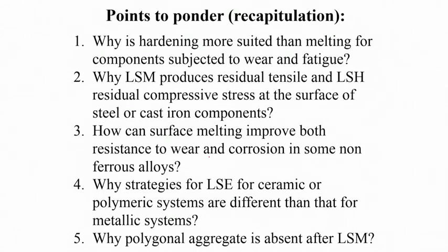summarize what we have discussed: hardening without melting as a strategy is more applicable to steel because it produces not only a predominantly martensitic microstructure, but also residual compressive stress, which is beneficial to improve resistance to both wear and fatigue.